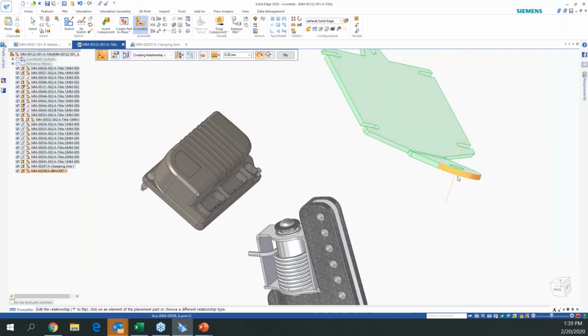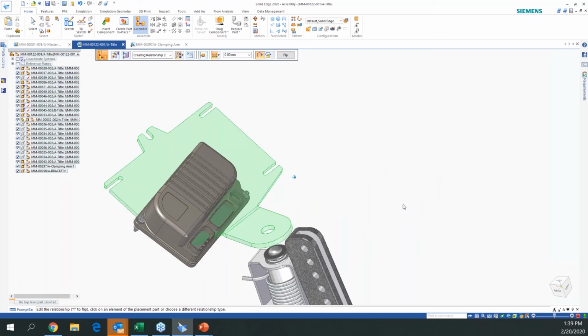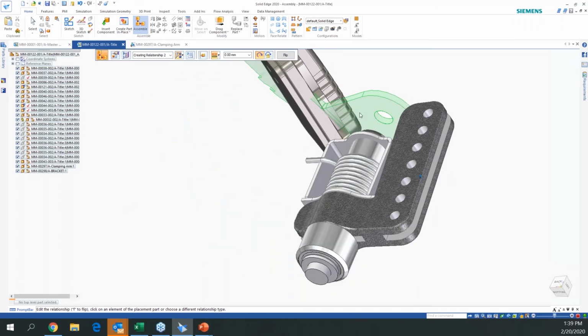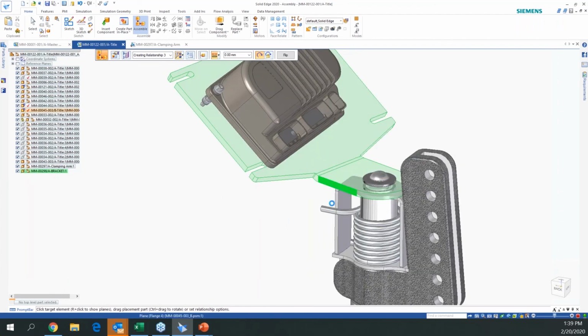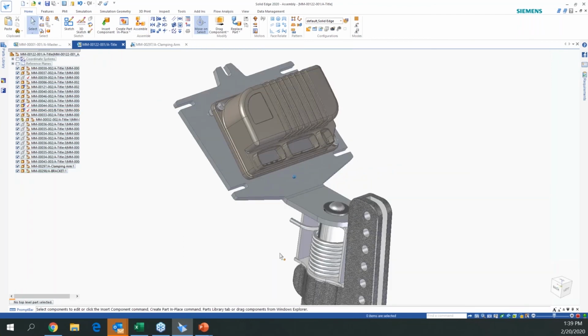You can see here now, I'm literally going to assemble this with my assembly. If I put my cursor on top of that radius here, I use my quick pick, my button number 3, and select my radius. I want that radius to match up to this radius. That looks great. Now I'm putting it into position. I want this face to touch this face, and I want this edge to line up parallel to this edge. That looks pretty good. Now I'm slowly putting this in a position.